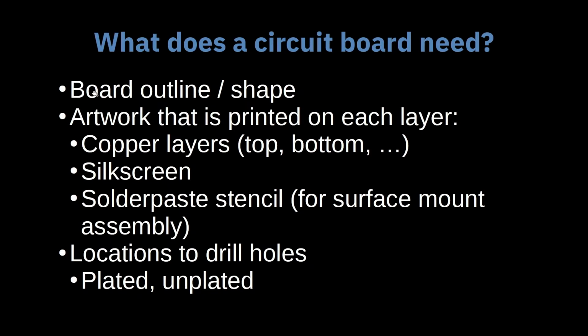And for us, because we're doing a lot of manufacturing in-house, we really care about things like the solder paste stencil, because small changes in when you put down solder before you put it into a reflow, when you're making a board, can cause a huge difference in your reliability or in your output. And so that's something that we really try to take care of. And it's something that works really well in a design tool because you can say, I want to update all the footprints on my board to match this new one we did. And you can be relatively sure that you got it. So that's one thing that we really wanted to use a tool for. And then you also need, of course, locations where you would drill holes to make vias.